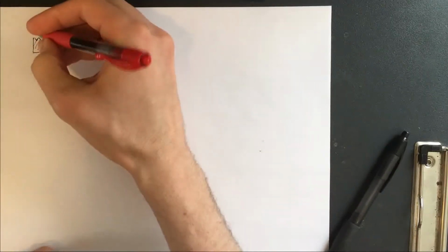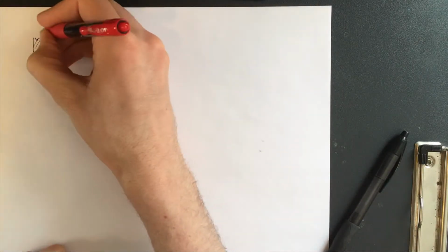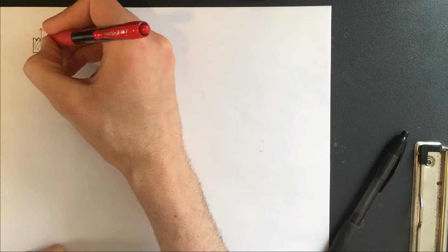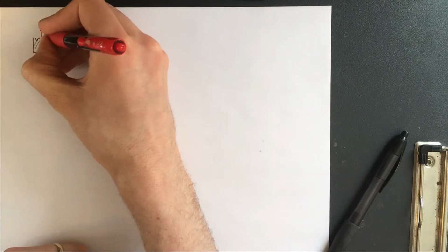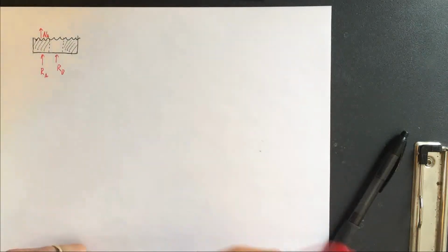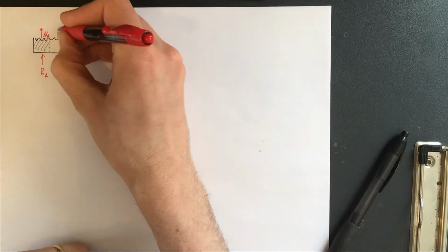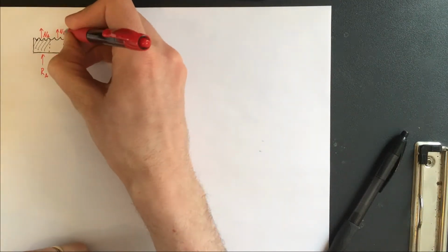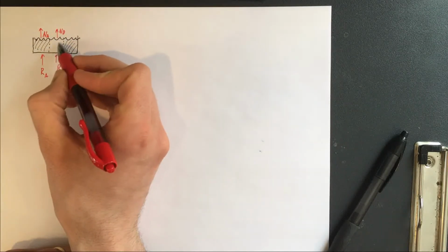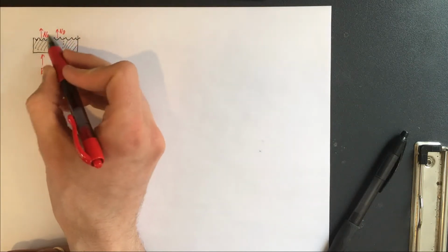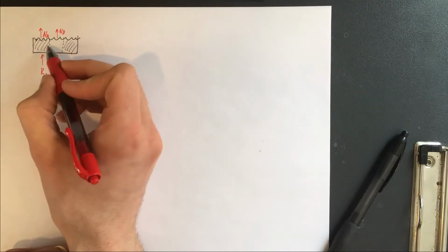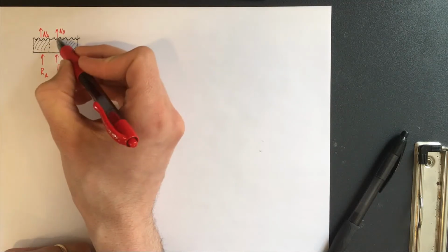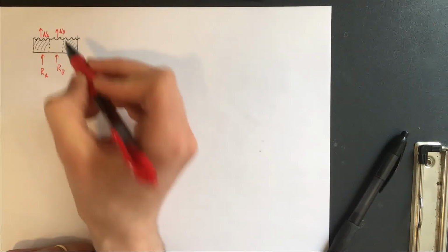we know there's some normal load transmitted through this part, which we'll define with our outward positive orientation, and we'll call this NA. And then in the brass, there might be a different normal load, NB. So these are the forces that are transmitted through each segment. The aluminum part, which would be this side and this side, because it's really an annulus that goes all the way around. And then NB, which is the normal load in the brass part of this, which is through this.